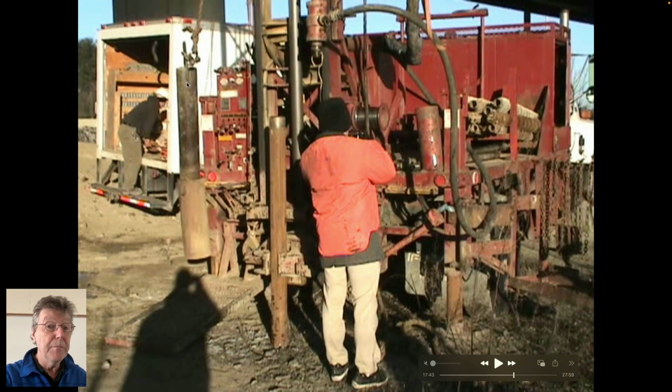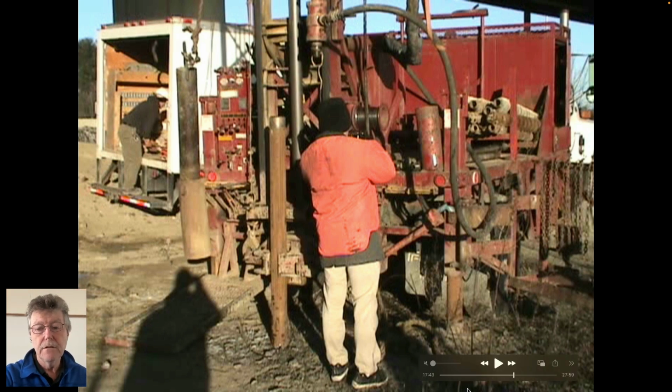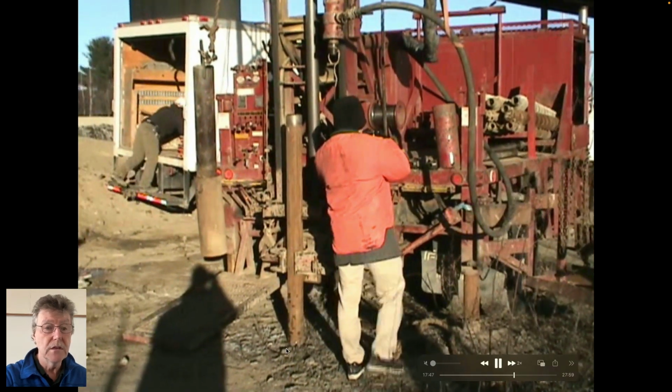This is the monkey hammer, which is just a big heavy weight with a thinner piece of pipe in the bottom of it that ultimately is screwed into here. The hammer is lifted up into the mast by wrapping a coil around this capstan here. When you tighten it, it pulls it up into the mast. You loosen it, it drops, etc. Very straightforward. You only have to see it once to know exactly how it works.